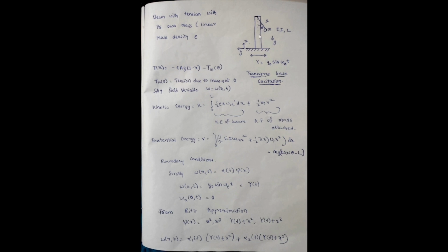Today I will be presenting the mathematical simplification of the tuned mass damper that we have just seen. So we start by assuming the working model as a cantilever beam, by the fact that the displacement gradient at the ground can be assumed to be zero, and also the mass attached at the top of the working model, in the case of damping, can be assumed as a pendulum attached to the cantilever at the top.